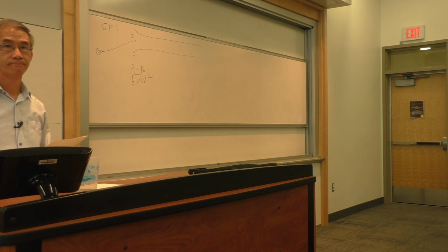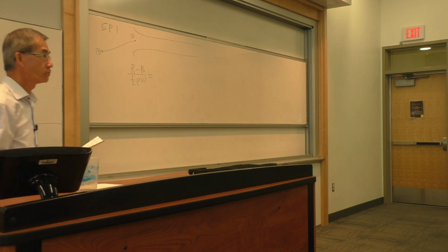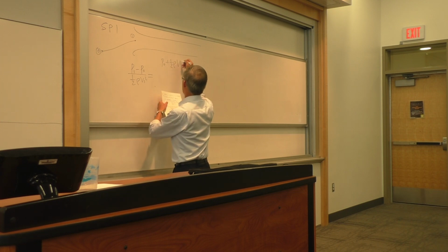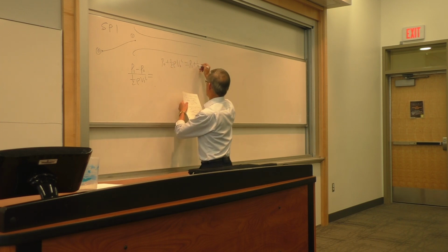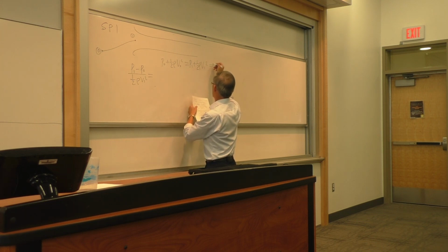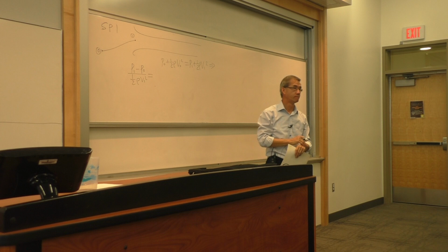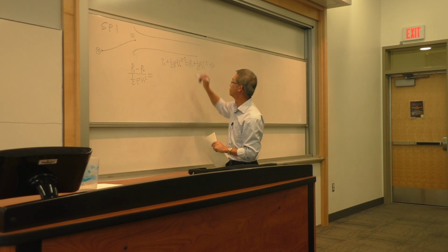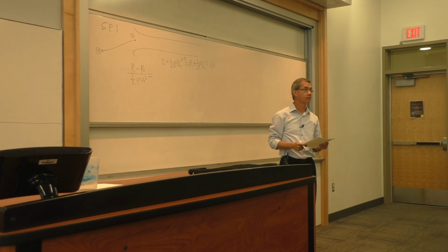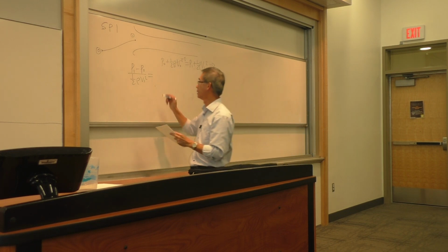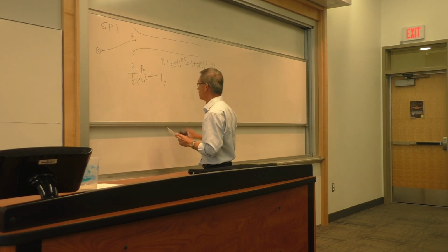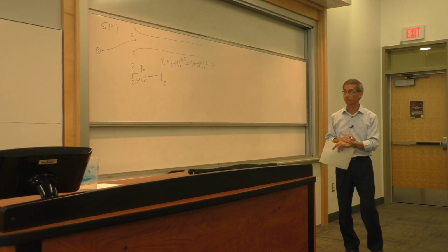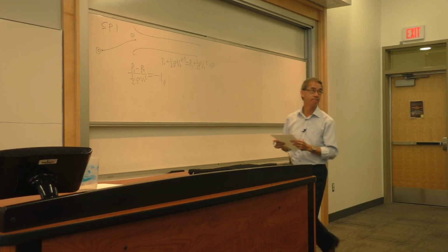What would you apply? Bernoulli. What is the velocity? 0? Far away from the intake? It's approximately 0. And so the algebra, very simply, when you work on that, will give you the dimensionless pressure coefficient of -1 for part A. All right?